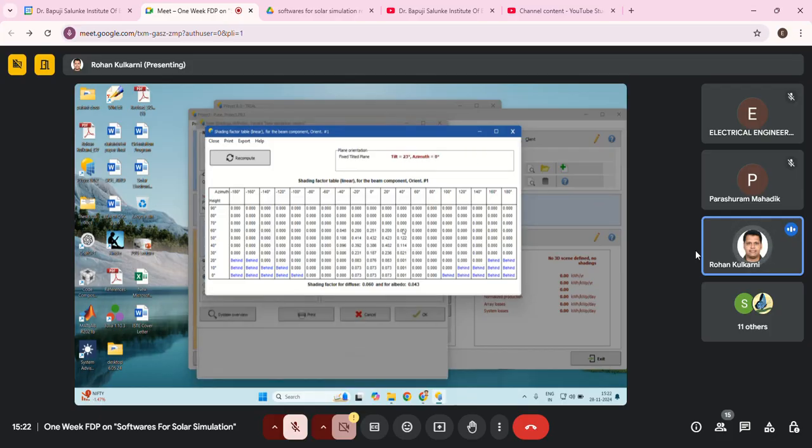Okay. Now, just getting the point. Whenever it says behind, it means the panel is going behind that particular tree object. Here you can see some numbers. Zero means there is no shadow on the particular panel. These other numbers are the diffuse radiation coming onto the panels, and based on that we are getting the values. Now we want to see. I'm going to recompute also. Okay, these are fixed.